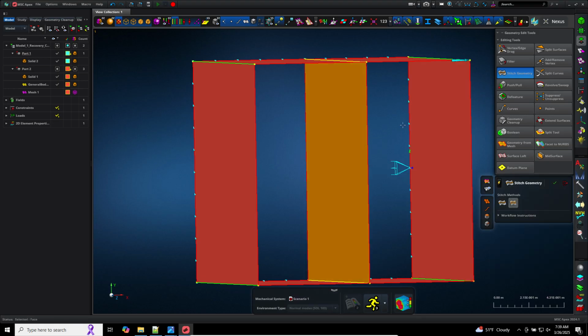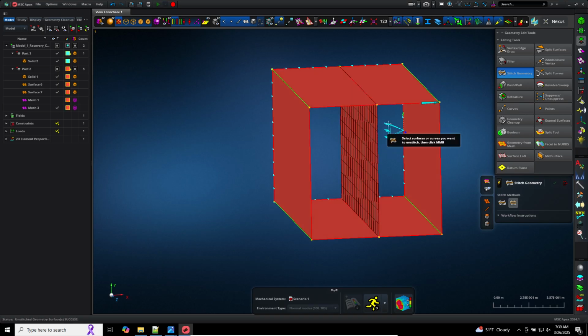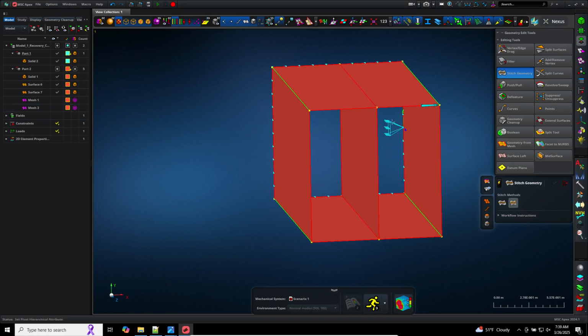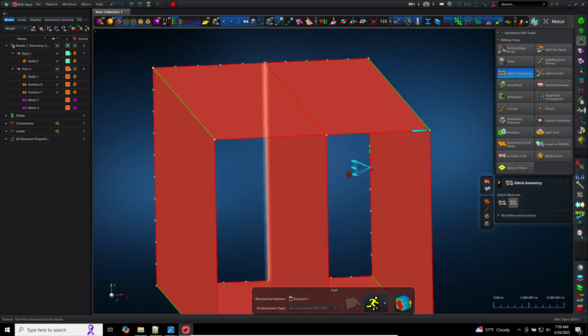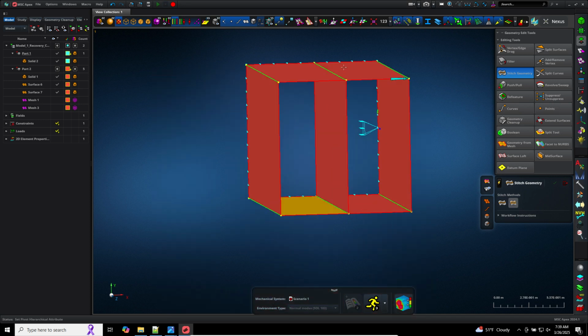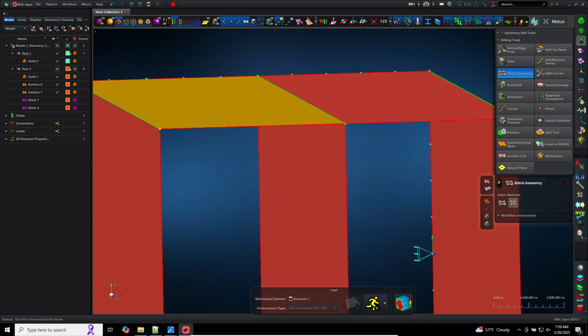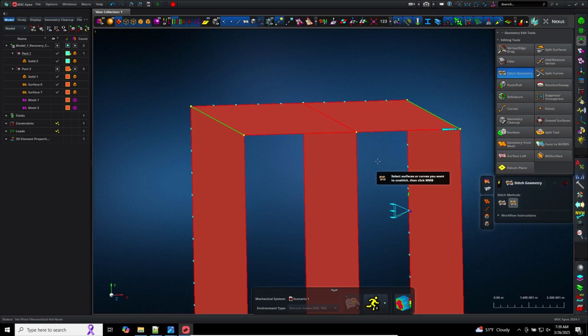We'll click this face, press the middle mouse button, and now that geometry has been unstitched. Look what happens when it's been unstitched. The edges are now red. And now this is very subtle. Here what you see is that it's green sometimes and then it's red sometimes. So I'll explain what's happening here in a moment.